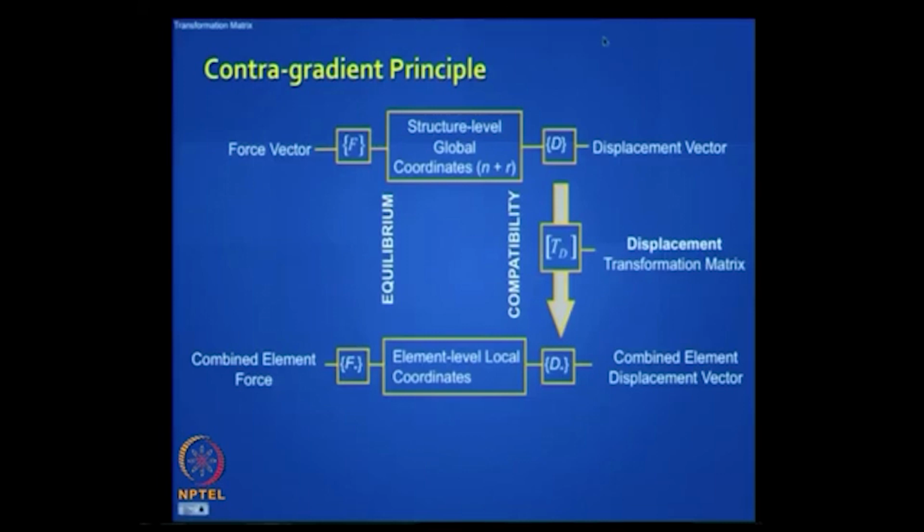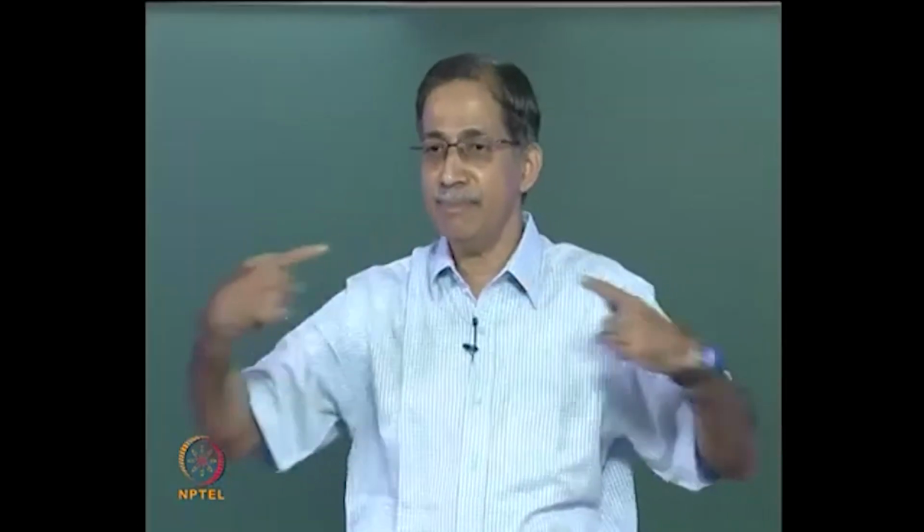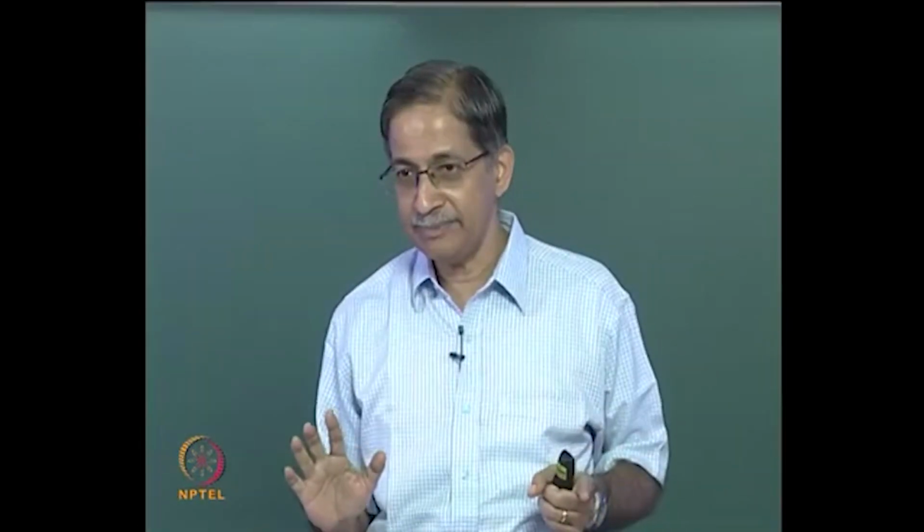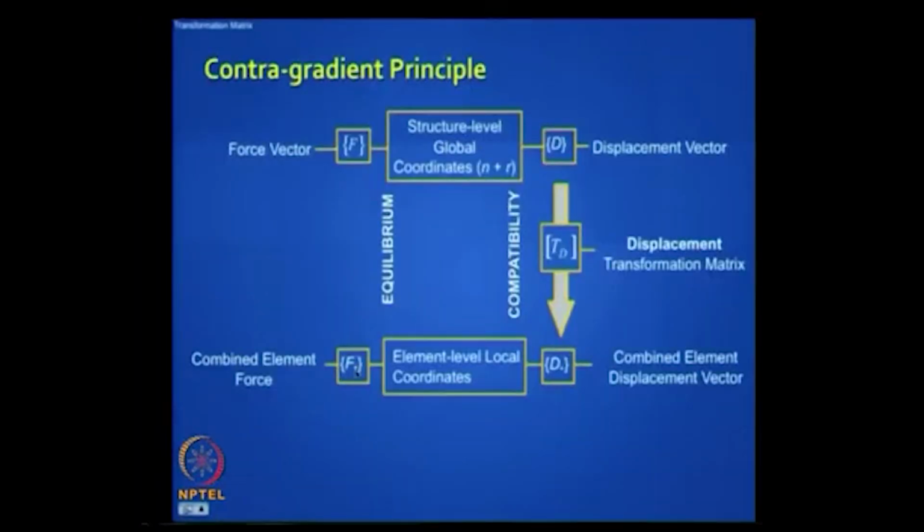Now the transformation we did was, if I know the joint displacements, then I get the individual member deformations, in this case the bar elongations, by applying the TD matrix as a transformation. I just demonstrated that, and this gives a compatibility relationship between the structure joint displacements and the member bar elongations. Likewise, there is a set of equilibrium relationships which relate F star with F.